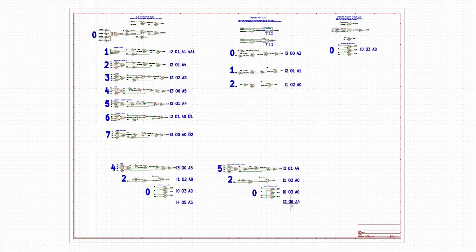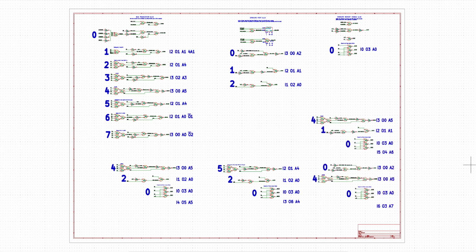Rather than having 2 OR gates left over, I can do the same thing, but have either 2 AND gates left over, or I could have one of each left over, 1 OR gate and 1 AND gate. So let me make those 2 combinations. These are what I think are the 3 likely candidates. Now I've got this one down here that has given me 2 extra OR gates. This one just to its right gives me 1 extra OR and 1 extra AND, and then the one above that gives me 2 extra AND gates.